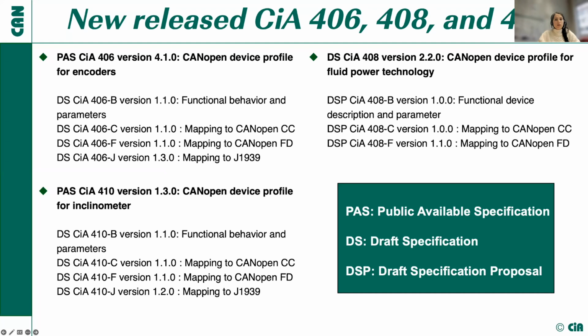And also in the 408, it is specified a CANopen interface for hydraulic proportional valves and hydrostatic pumps and the hydrostatic transmissions, and this profile may also be applied on pneumatic devices as well. And the 410 specifies the interface for single and dual axis inclinometers.